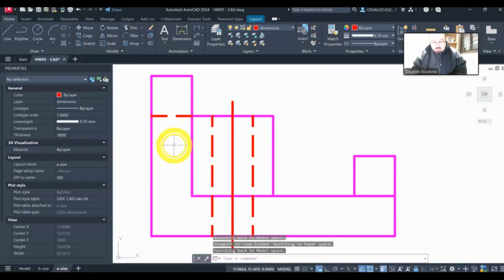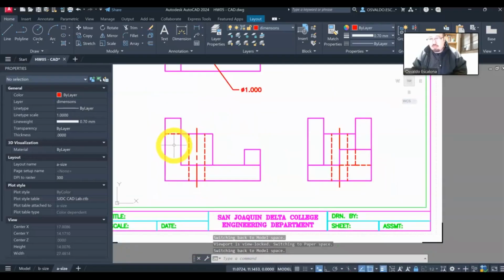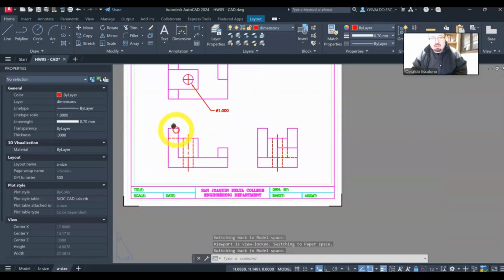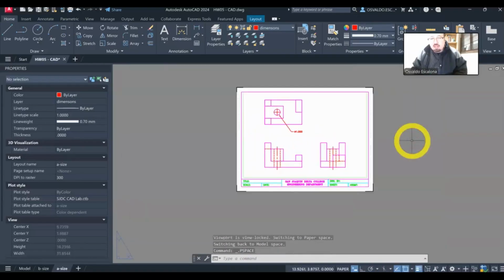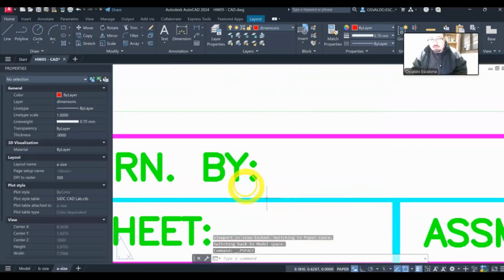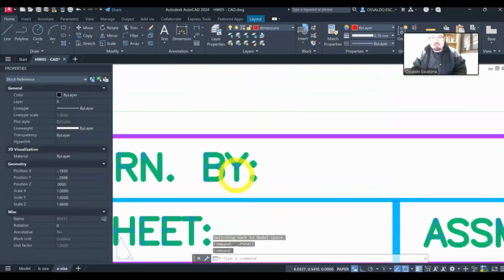So we'll change the spacing, maybe a little bit better. Maybe LTS 1. There we go. Change it to LTS 1. Yep, looks pretty good. I'm going to move away. And at this point of time, you can type your text, your information. If I click on it, you guys will notice that it doesn't let you do it.